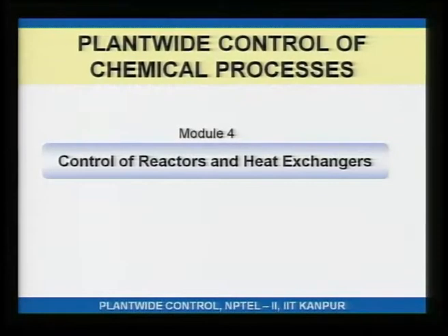Why is it heat management? It's because the reactions can be exothermic, or usually are exothermic, sometimes highly exothermic, and how do you remove the heat being generated inside the reactor? That becomes key to stable effective operation.